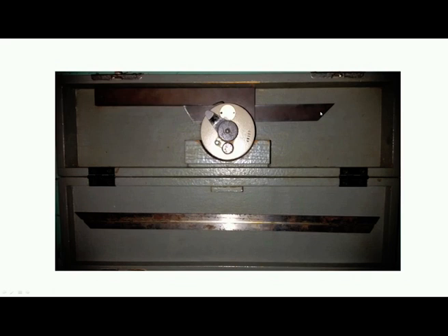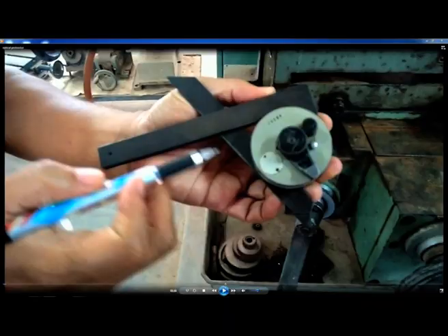Now, we will conduct an experiment to show how to use optical protractor. Now, you can see this is the milling machine table. I am trying to measure the inclination. So, this is the guideway. We have the top surface of the guideway and then we have an inclined surface of the guideway. I am trying to measure the inclination between these two surfaces using this optical bevel protractor.